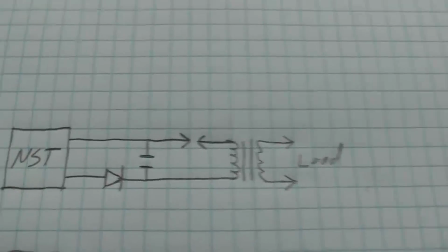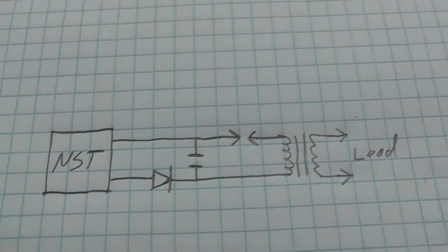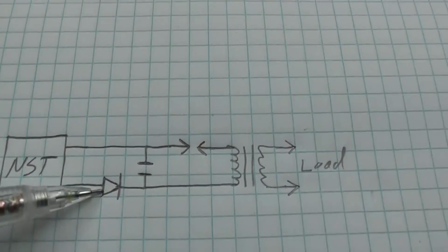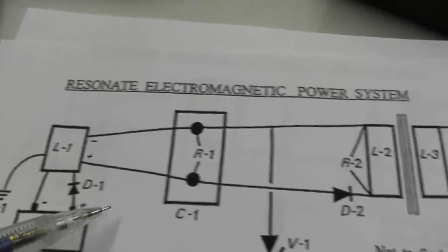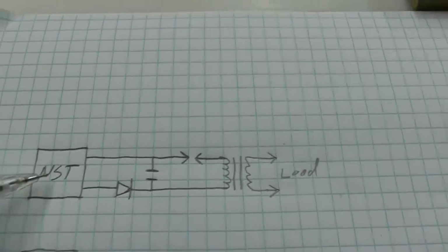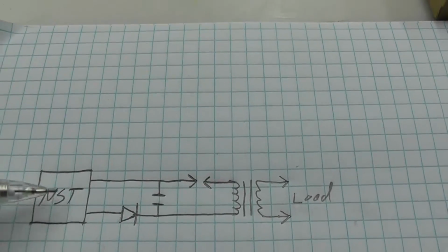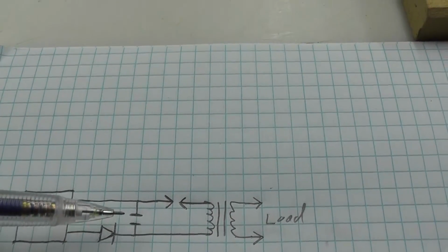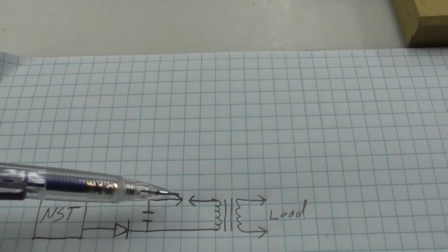What I have laid on that table is this here. It's a fairly simple circuit, similar to the one that's over there. However, you can see that the diode is moved. If you don't put this diode here, which is after the capacitor, instead of here, then the NST shuts off. What I'm doing here is taking the voltage from this NST and charging this capacitor, and it charges in one direction and then discharges back through the transformer when it hits a certain voltage, depending on this gap.